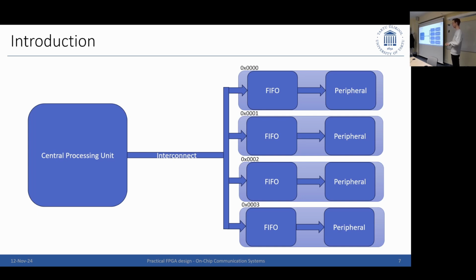So we have on the chip our own communication interfaces, and usually you want to standardize them as much as possible because it makes it more efficient. What that allows us to do as well is that we have standardized blocks. So we can have the same bus interface for all of these blocks, and we just give them different addresses, and then everything is very simply routed through. So ideally, our communication protocol, which we send to the peripheral, would include the address as well, and then we could just decode it according to the bus, which the bus can automatically already do, and this makes it all very simple.